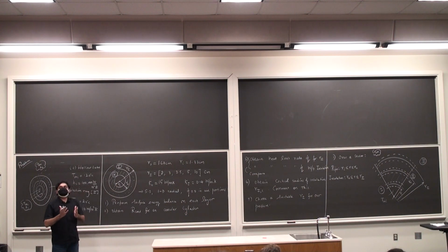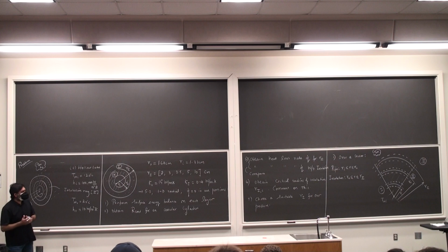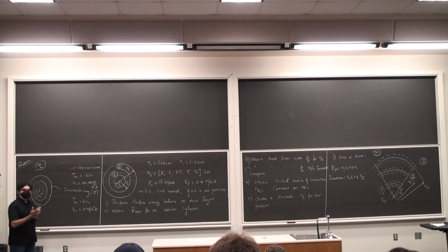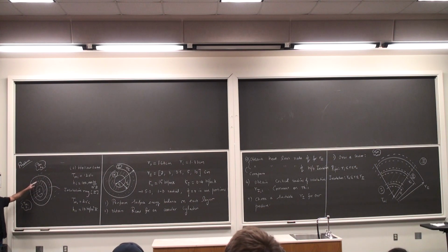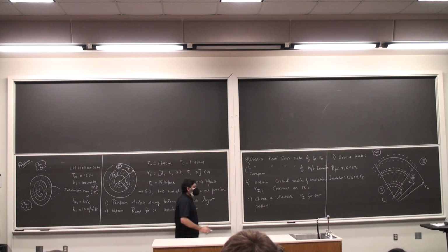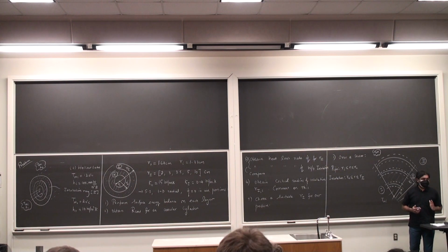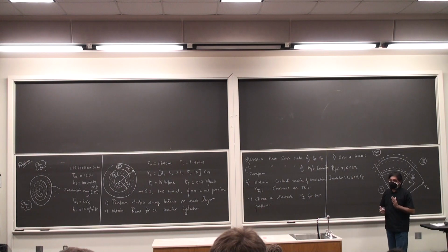Then all I have to do is draw the arrows. In many problems, most of the times, one can use intuition to figure out what the direction of heat flow is. Okay, in a problem like this, it is fairly straightforward to understand that there is no energy generation taking place in any of these rings. This fellow is hot, that person is cold, so the heat transfer rate is going to flow radially from the hollow piece all the way to the ambient. Okay. In certain other problems, it may not be possible, which means that you need to let the math do the talking. Okay, so you choose a direction for your heat transfer rate, and then you let the equations figure out, okay, is this right or not, based on the information given to you. Alright? So for this problem, it's straightforward.